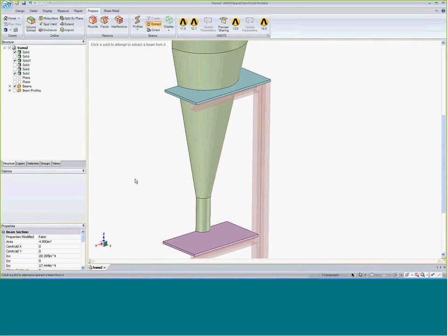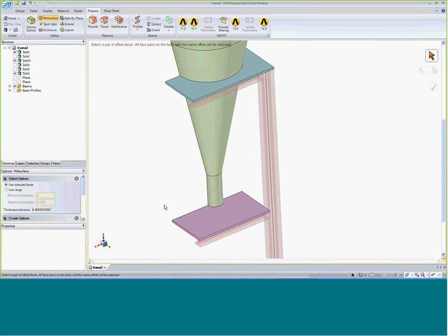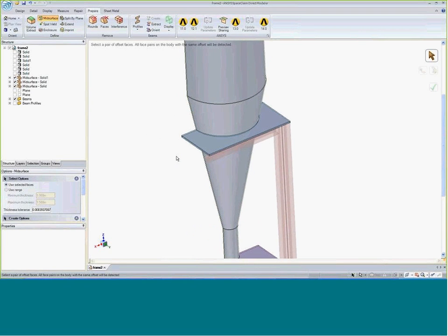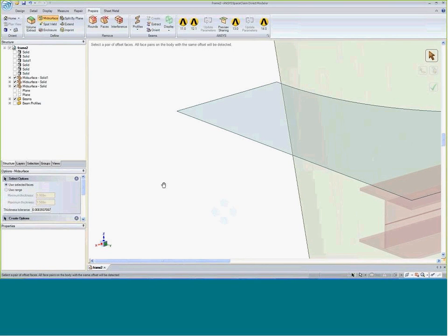We've got some beams in here. The next thing is I will take these other solid bodies and then get a mid-plane surface out of them by identifying those surfaces. There is an automatic way to search through all the parts here, but I have a couple, so I'll just do that manually. So then down here again, you can see this body that used to be there, and now it's represented by this mid-plane surface through there.